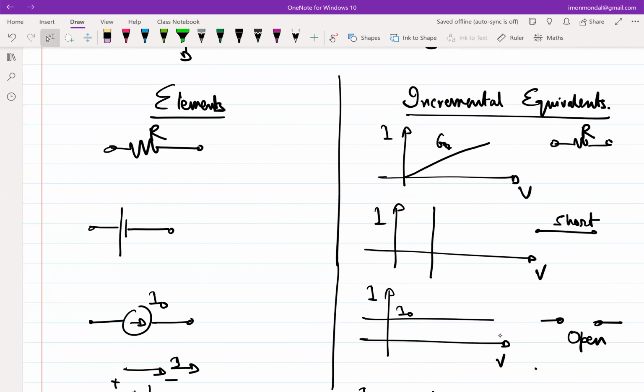So let's assume that this resistor here is obviously a linear resistor. That's why the IV characteristics was a straight line, right? So had the IV characteristics not been a straight line, then I would have had to replace this nonlinear resistor with a linearized equivalent, whose value would have been 1 over slope of that IV characteristics, right?